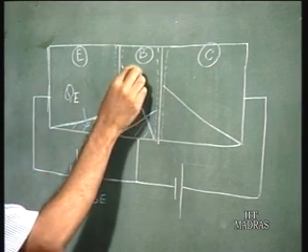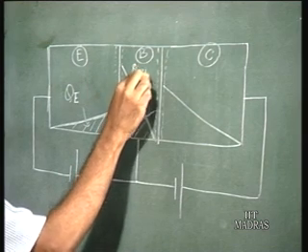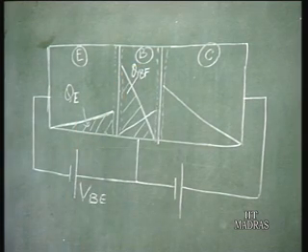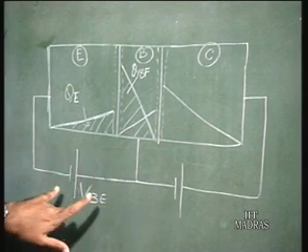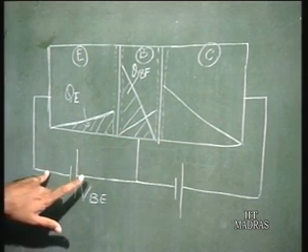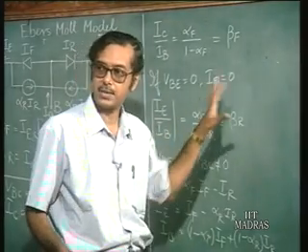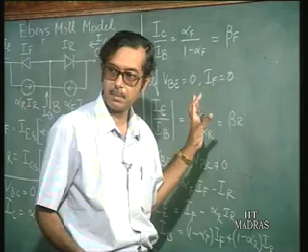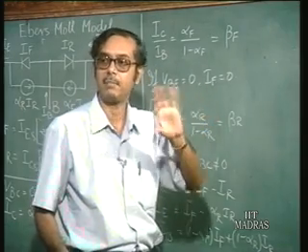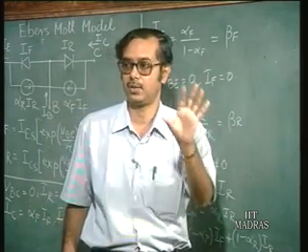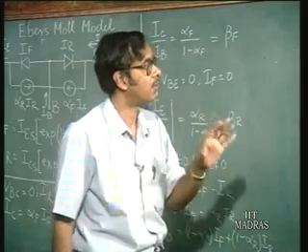this is QBF. The F actually stands for the forward case, that is when you have the emitter base junction applied voltage. All right. We have seen that you have two cases when you have the emitter base voltage applied and the base collector is 0, we call that the forward case, forward mode of operation.